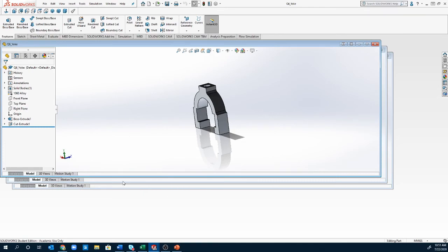One important thing is that when you're building assemblies, it is much easier if you have the part files open while you're working, as opposed to just simply adding the part files later. When we build our assembly, any updates that we make to the parts in the process will automatically update in the assembly, so this allows us to do some interesting tricks.